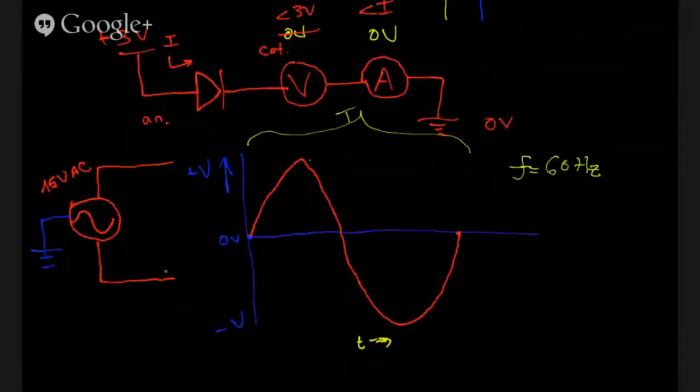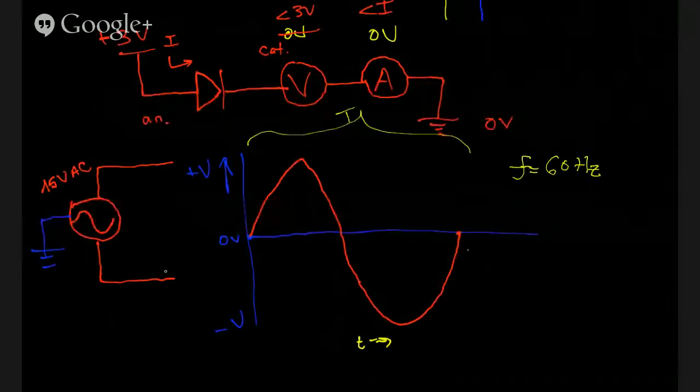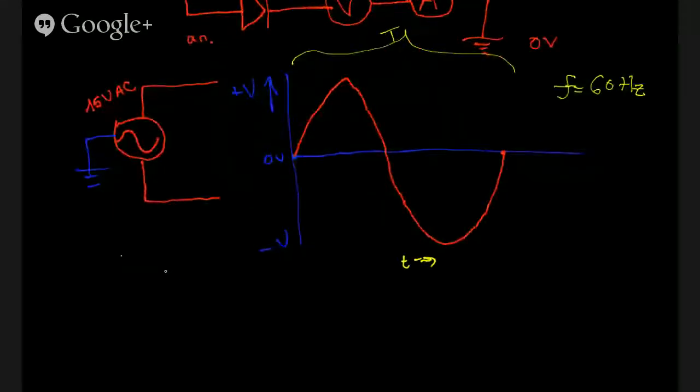And let's say we wanted to turn this alternating current into a direct current, like what we get out of a battery. There's a lot of applications where we have to use DC as opposed to AC, alternating current. So we want to rectify this. We're going to go from 15 volts AC, which isn't peak to peak. Actually, we got the RMS value.